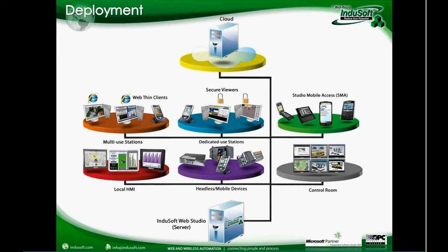Studio Mobile Access is the solution for non-Microsoft devices like Androids, iPads, iPhones, and the current solution allows you to visualize and even change tag values in real time, and allows you to visualize and acknowledge alarms also in real time. And we are improving the solution, evolving the solution right now to add additional graphical capabilities, to monitor online trends and history trends, see graphical screens on the device, and visualize even dashboards on a non-Microsoft device using just a web browser.